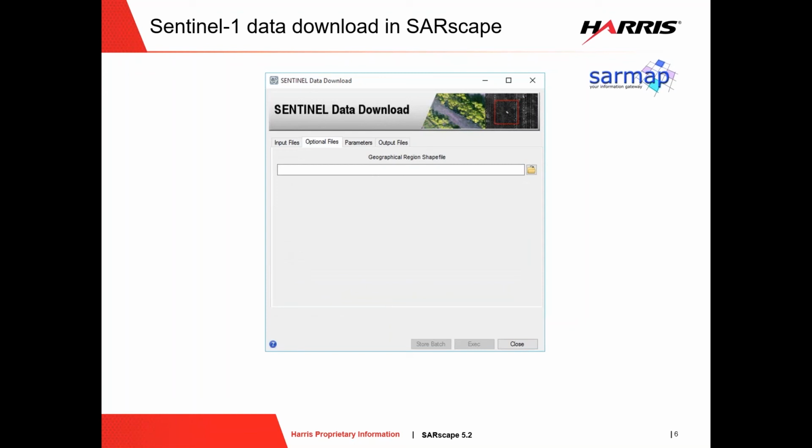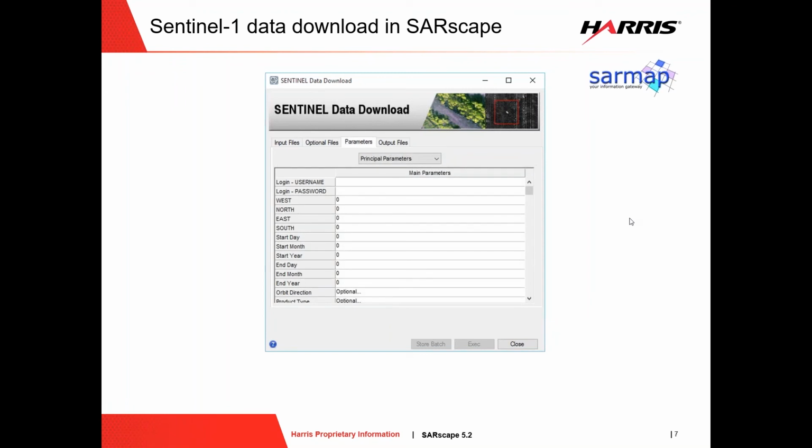So you can provide a polygon or several polygons saying, yes, I am interested in this geographic region. Of course, you're allowed to provide your username and password. This is going to register you inside the Sentinel Scientific Hub, and you can also specify in coordinates your region of interest, your period of interest, start and stop, day, month, and year for the selection, and all the options, such as whether you want descending or ascending, all that you can use to refine your search.